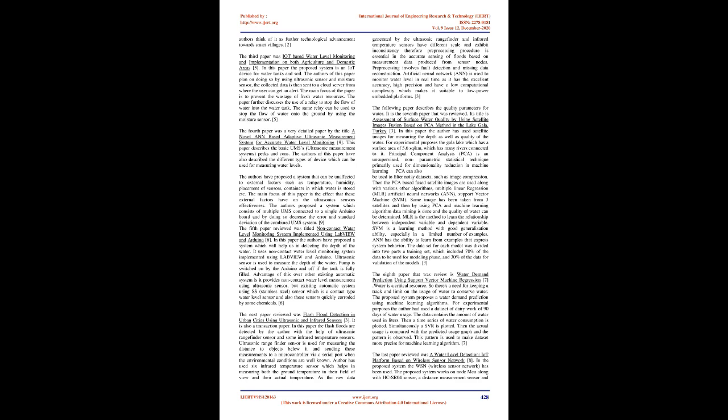In this paper the authors have proposed a system which will help us in detecting the depth of the water. It uses a non-contact water level monitoring system implemented using LabVIEW and Arduino. An ultrasonic sensor is used to measure the depth of the water. The pump is switched on by the Arduino and off if the tank is fully filled. The advantage of this over other existing automatic systems is that it provides non-contact water level measurement using an ultrasonic sensor, whereas existing automatic systems use stainless steel sensors, which are contact-type water level sensors and also quickly corroded by some chemicals.